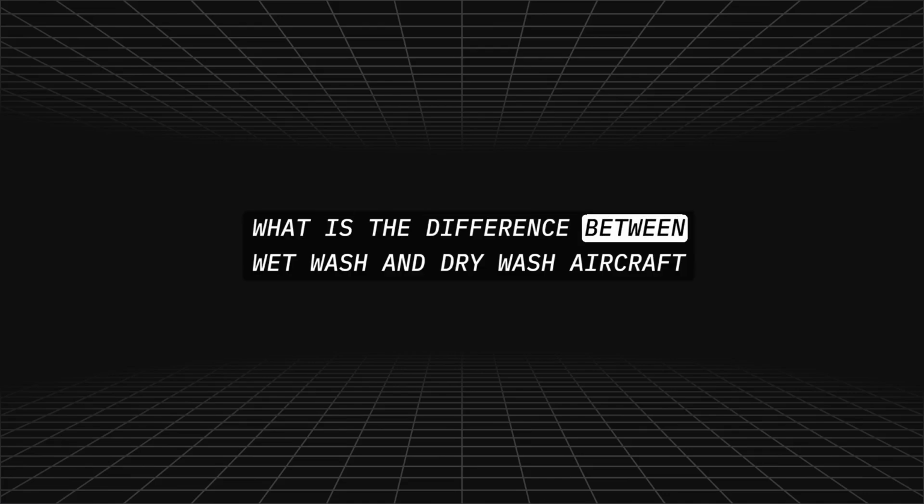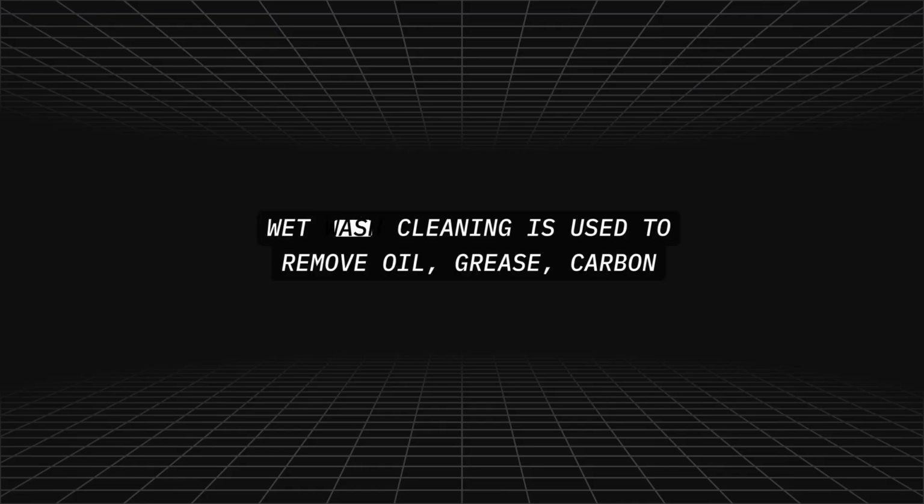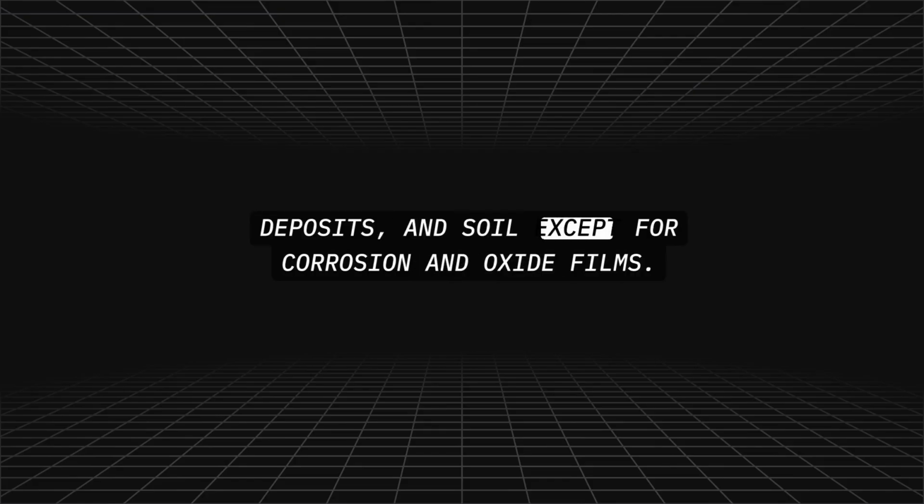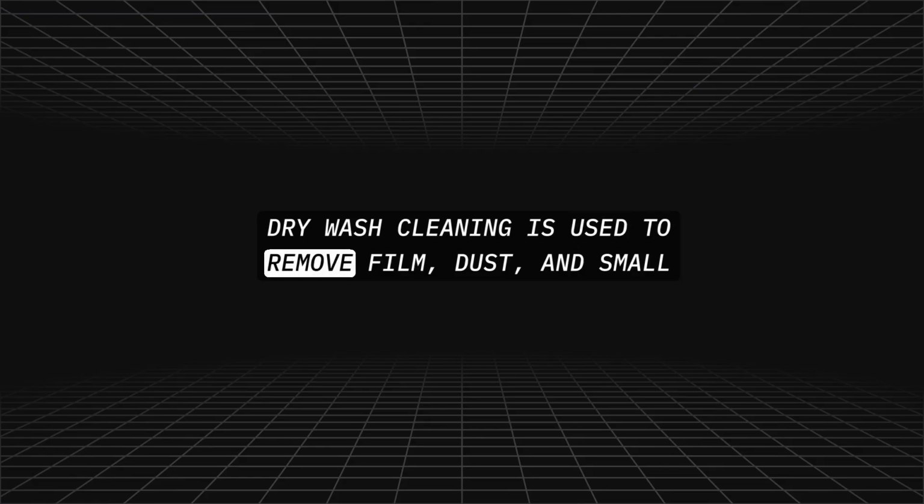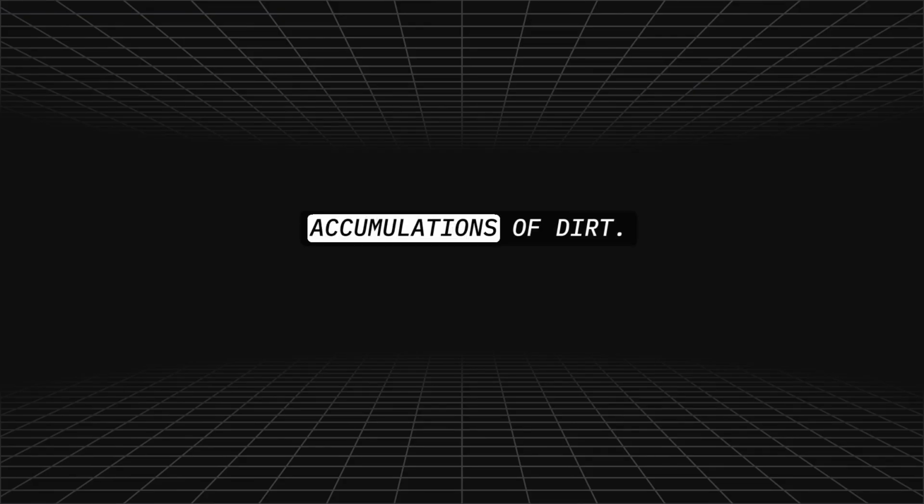What is the difference between wet wash and dry wash aircraft cleaning? Wet wash cleaning is used to remove oil, grease, carbon deposits, and soil, except for corrosion and oxide films. Dry wash cleaning is used to remove film, dust, and small accumulations of dirt.